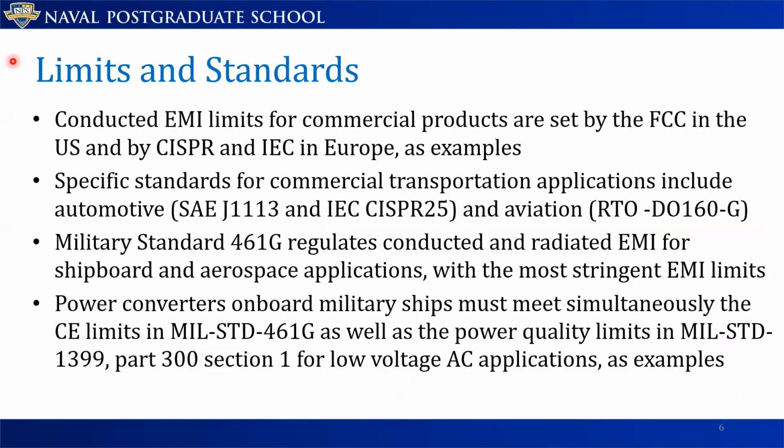So there are limits and standards for conducted EMI. We want to reduce them, and so in the commercial world, for commercial products, there are limits set, for example, by the FCC in United States or by CISPR and IEC in Europe. And these are just examples. There are also specific standards for specific applications, such as commercial transportation applications, like automotive. And we have the SAE J1113 standard or IEC CISPR 25 in Europe, and also aviation standards, of course. These are all EMI standards meant to limit the production of EMI in a product that is being sold in different countries and for different applications.